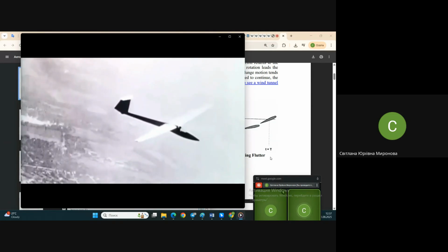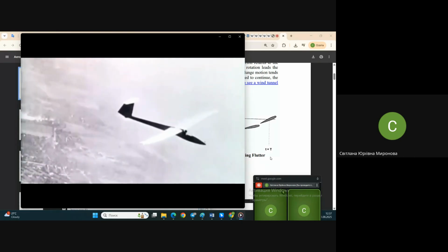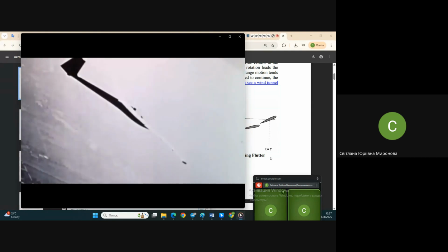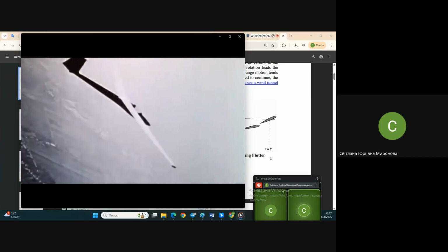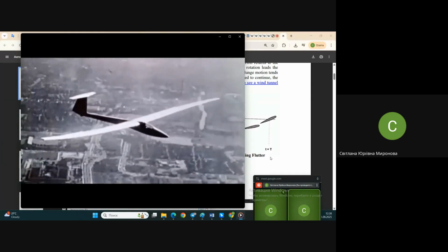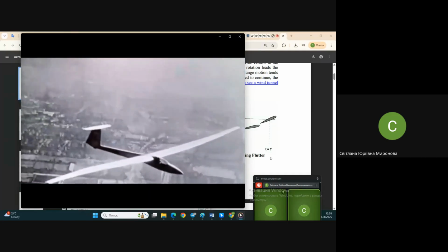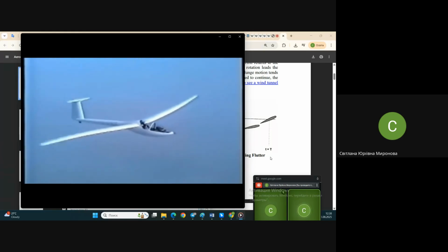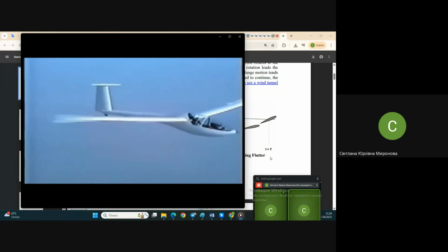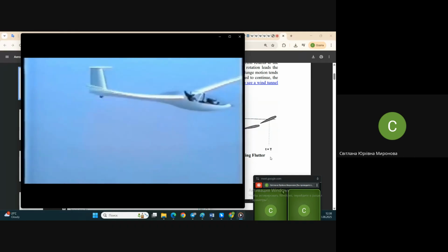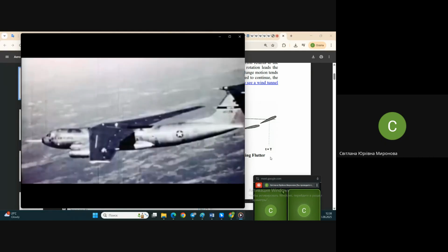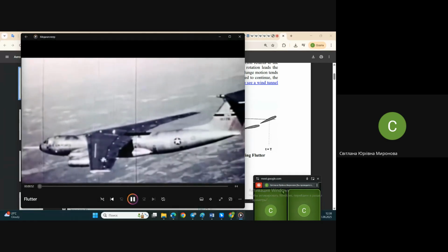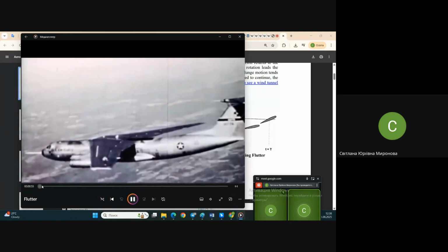In this case, it's not the stabilizer, it's a wing. Fluttering, and you see it all over the wing. It looks like not just oscillation, it's combined with both bending and torsion. Now it's another airplane. Look what happened. At some speed, trembling of the ends appeared. Quite clear, it's already really fluttering, the whole wing is fluttering, look. And it stopped. Let's take attention once again to that place.